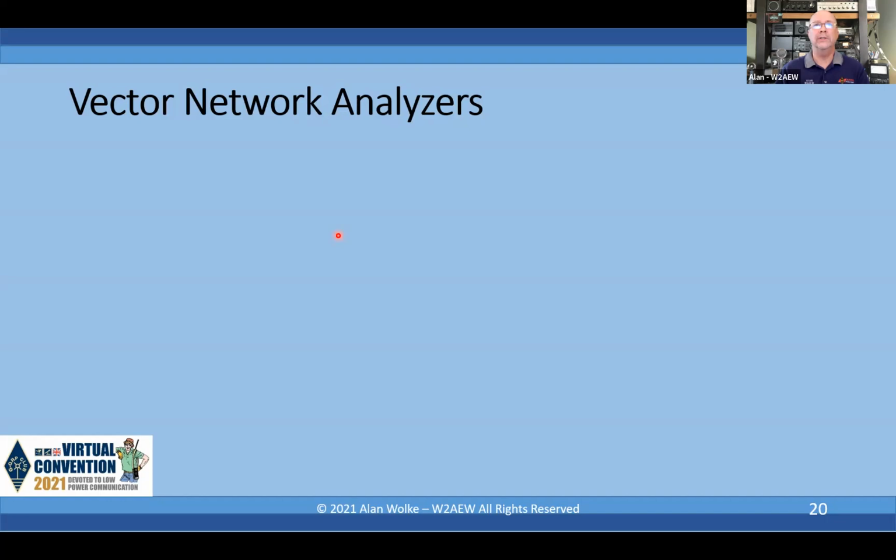Thank you. Let's see. Recommendations for an affordable spectrum analyzer for the amateur? The Rigol DSA815 is about a $1,500 US unit. It's actually pretty good. I know there are less expensive units out there. I just don't have direct experience with them to be able to recommend them, yay or nay. But if you want to get in really cheap, the Tiny SA gets you 80% of the way there for less than $100 US. As processing power gets cheaper, will analyzers move to more real-time analyzer designs? Absolutely, and we're seeing that in the professional world as well.